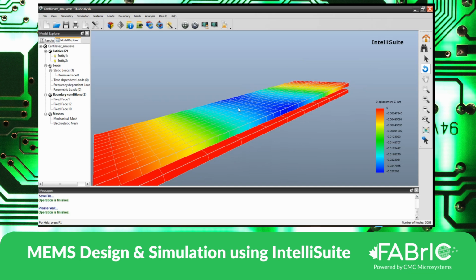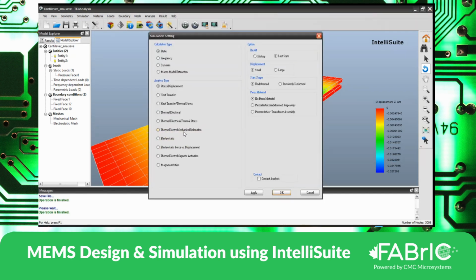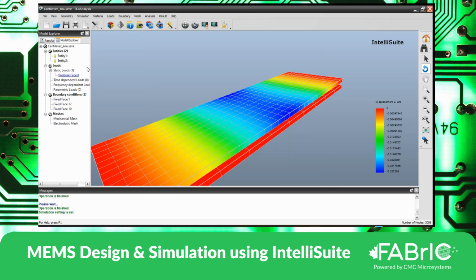Same goes with a capacitive type of pressure sensor, whether it's planar circular or planar rectangular. The simulation setting goes as it is. In the case of a capacitive pressure sensor, we select thermo-electromechanical relaxation, and then we apply pressure and also apply voltage.